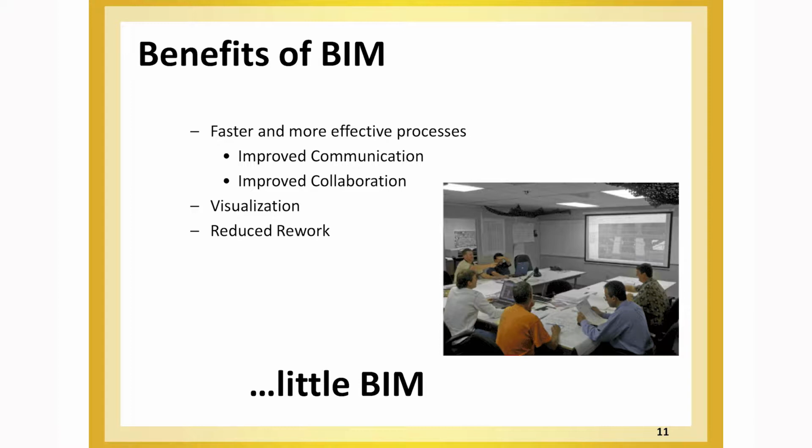It's curious why you said that. When you guys are modeling, are you ever modeling conduit, or is it just to a certain size? It depends. In the BIM execution plan, we would define roughly conduit sizing. We tend to not model anything under 2.5 inches. That's typical. So it's not modeled. It just goes away.